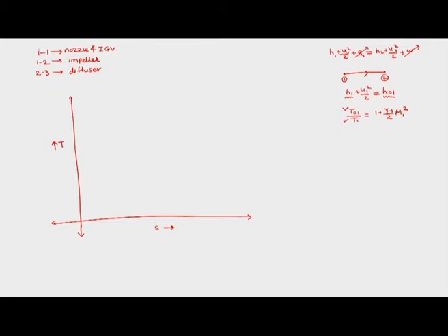This relation can be proved from this expression where we are taking h is equal to Cp into T, where Cp is assumed to be constant, the gas is assumed to be calorically perfect, and accordingly if we derive, then we will get a relation which is 1 plus gamma minus 1 by 2 M square. So here we are having static temperature, here we are having total temperature.